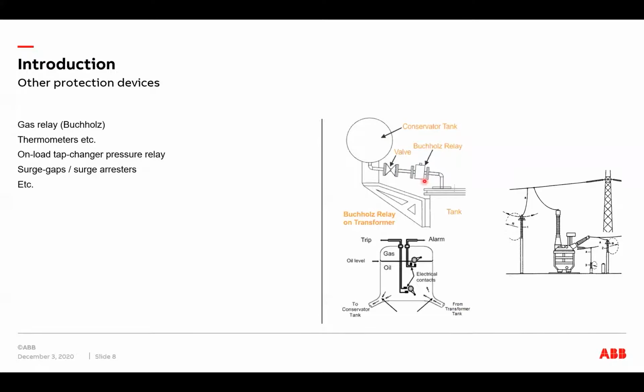And the purpose of the Buchholz relay is that when there are some flashovers in the power transformer, a gas will be generated, and this gas will flow here into the Buchholz relay and get trapped inside.